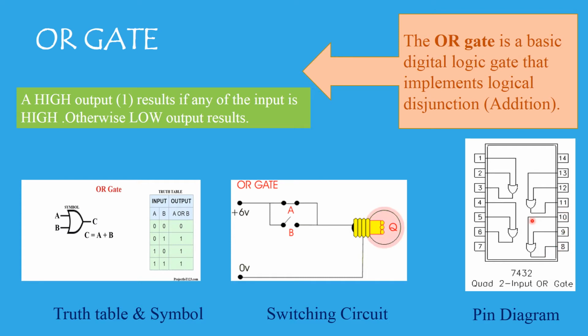So remember, this is purely for your laboratory purpose. When it comes to implementation, you have to remember the basic IC numbers and the pin diagram. Only when you connect it in this way, you'll have the outputs to be seen. If you connect an output wire to either of the inputs, at times it will get a short circuit or it won't perform its function properly. Next we will see the